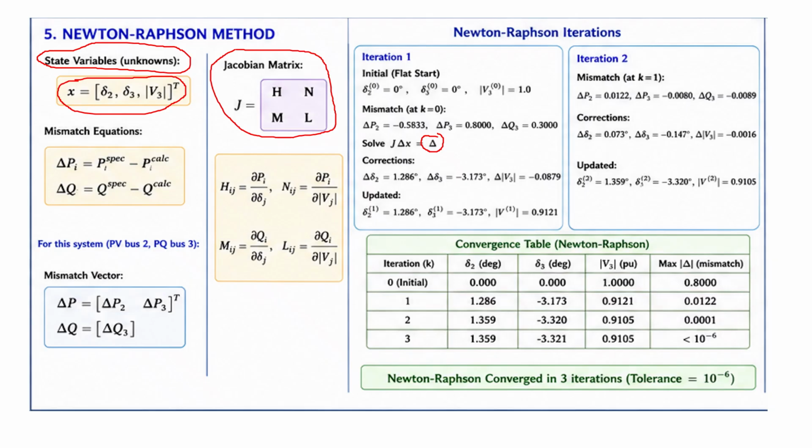If the magnitude of the voltage difference or angle difference is greater than the tolerance value, we'll calculate the new update. Like that, we will go for that. So initially we have this voltage magnitude, then this voltage magnitude and the current. Now we update it by solving the Jacobian matrix. Jacobian matrix times the correction factor minus f of x equal to 0.